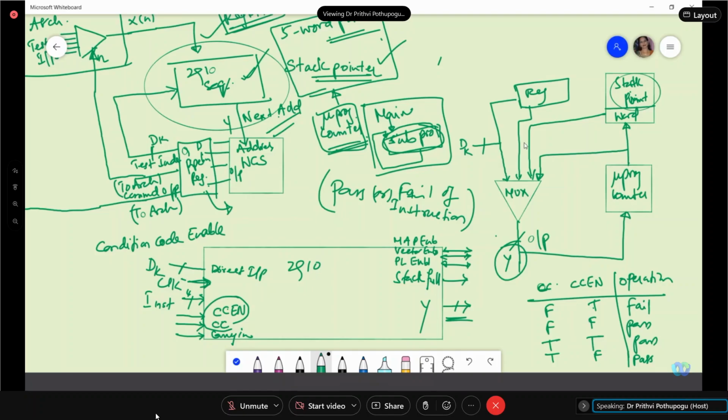So altogether in this microprogramming, we have taken the single qualifier, single state instruction, where earlier it was multiple qualifier representations. We refined that into a single qualifier per state instruction. Then later we refined it into a single qualifier, single address microinstruction.